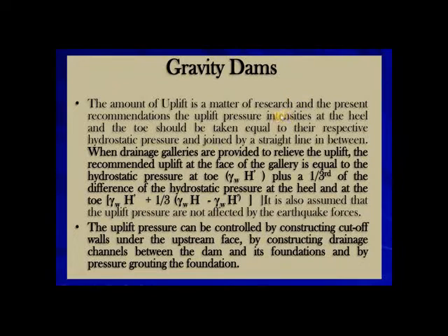The amount of uplift is a matter of research, and the present recommendations are that the uplift pressure intensities at the heel and the toe should be taken equal to their respective hydrostatic pressures, which we calculated. When drainage galleries are provided to relieve the uplift, the recommended uplift at the face of the gallery is equal to gamma WH dash plus this one. It is also assumed that uplift pressures are not affected by the earthquake forces.